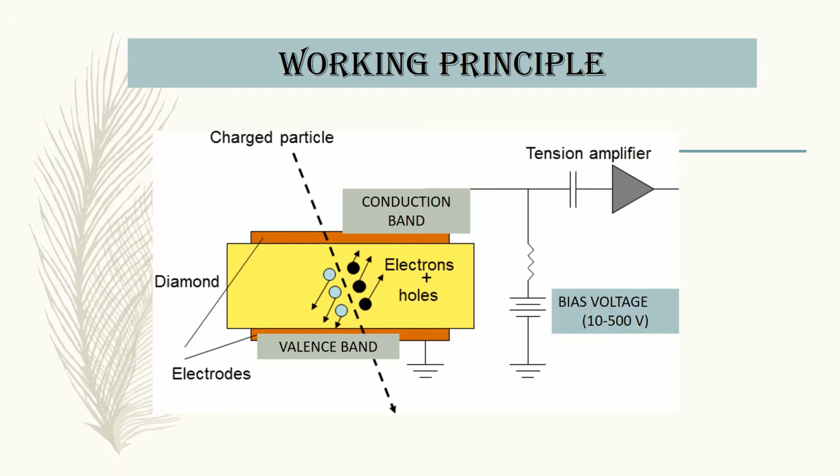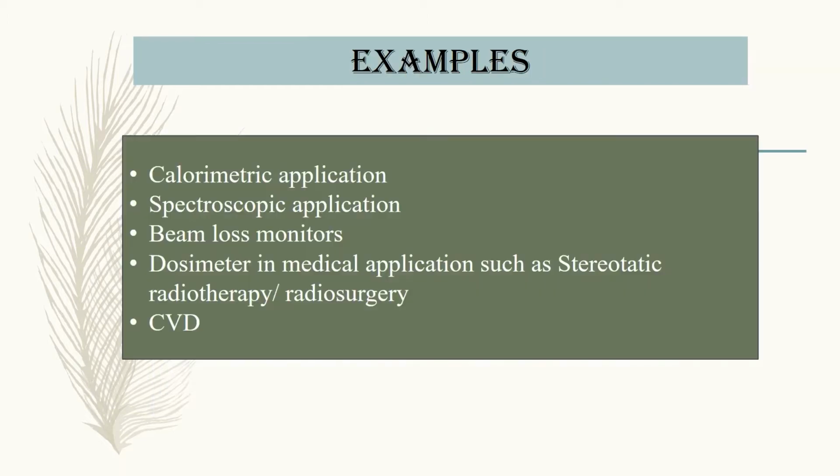The increased number of space charges as the diamond is irradiated causes a decreased bias and thus a decreased charge collection efficiency, which will give a decreased signal from one measurement to the next. When the traps are filled, all charges go to the electrodes and increase the output signal.